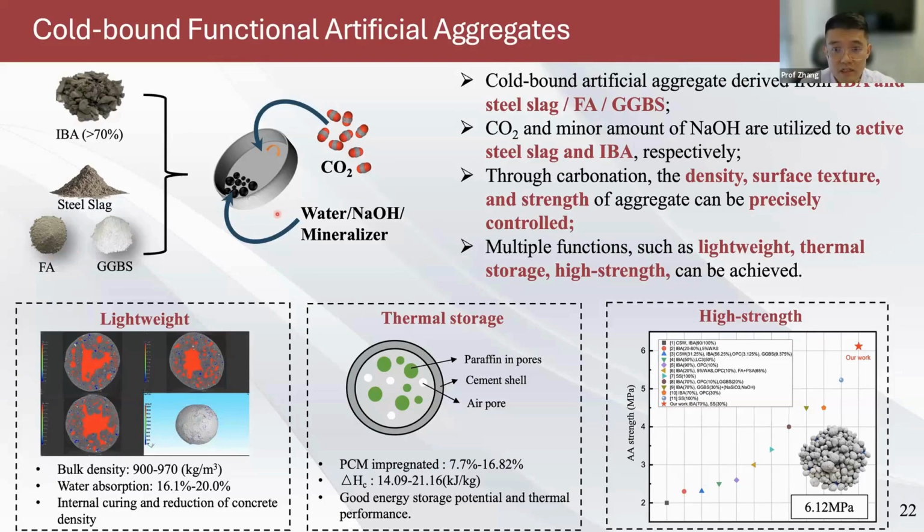We can actually achieve multiple functions, including lightweight. We can control the porosity of the artificial aggregates and make them hollow. The highlighted areas on the right are actually hollow. So we can achieve a lightweight feature of our artificial aggregates. Also, we can achieve thermal storage. We can produce thermal storage artificial aggregates.